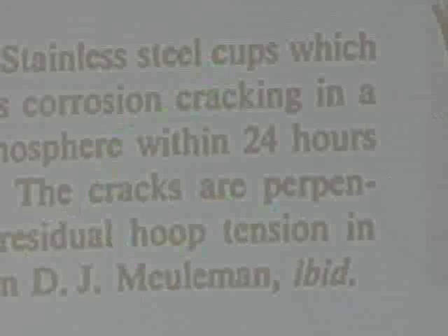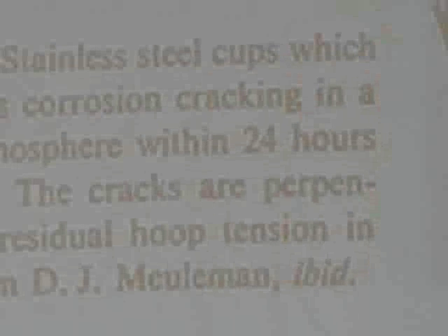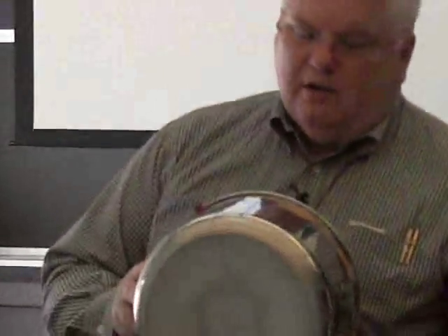And in fact, I didn't know that this was in Hosford's book at the time, but these stainless steel cups with stress corrosion cracking in a laboratory atmosphere, within 24 hours after drawing, the cracks are perpendicular to the residual hoop tension stress. So they had that. The Farberware pots had cracks like this, and I don't know if they formed within 24 hours, but they put them on a boat, they shipped them to Japan, and when they came off the boat, they had cracks running down here.